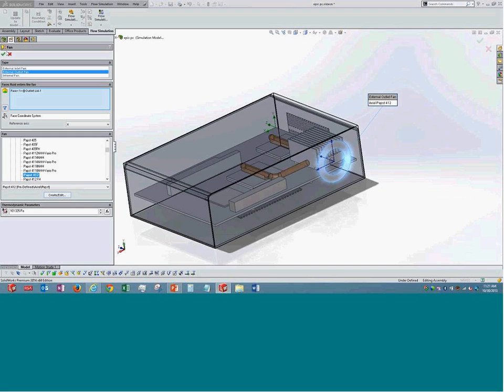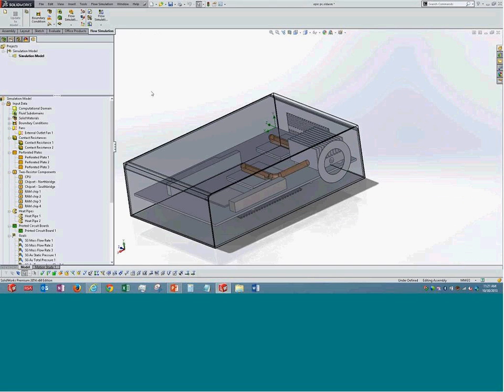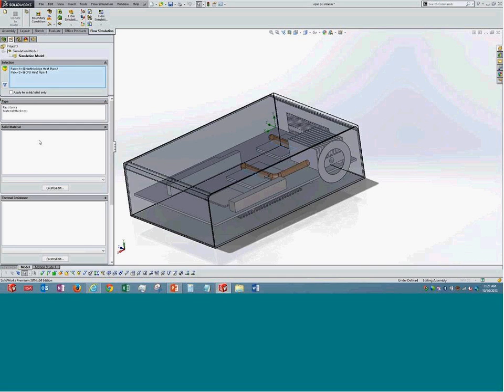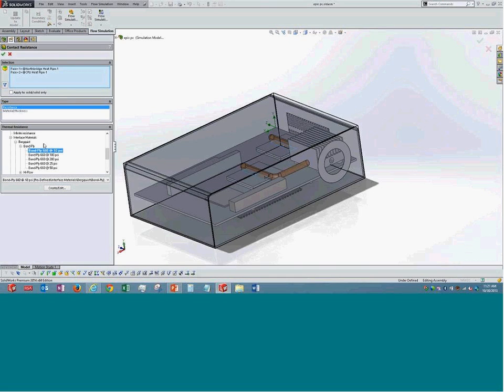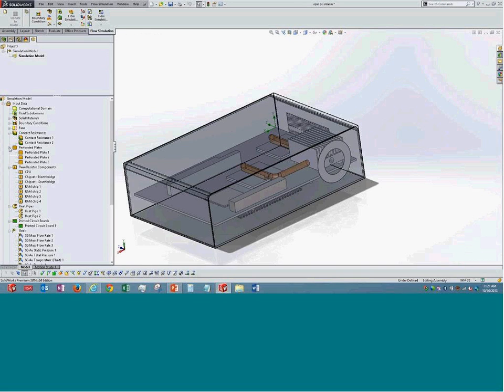In simulation, we use the two-resistor component to represent the chips, and they are used to create the heat inside the system. And I have heat pipes which are used to efficiently dissipate heat out of the chips into the heat sinks. And printed circuit boards, and we have the options to specify layers inside PCBs. We also have a few ready-made PCBs over here. We can specify the amount of connecting layers present in these particular boards.